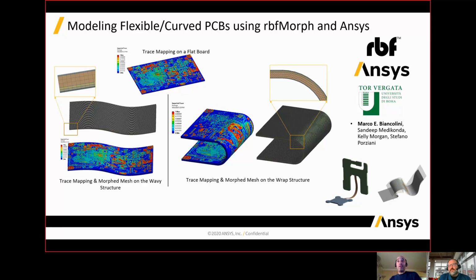The approach in Sherlock is you basically model it as a regular PCB with trace modeling in the middle, and then you can connect them together in Mechanical and run all of the analyses that you want, the bending analyses. And because Sherlock creates the traces as is, you can actually bend them. What I think is really cool is that this workflow is enabled by the fact that connecting different PCBs in Sherlock is very, very easy. Splitting up portions of a PCB is very easy.